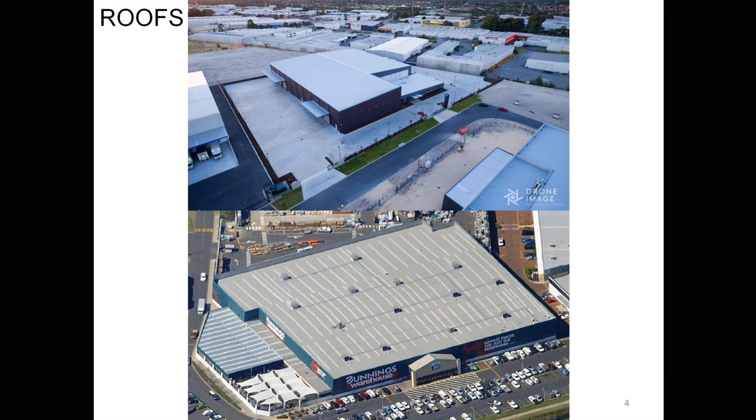Yes, it's called a siphonic system, and of course the most common use of siphonic systems is actually in American toilets. If you ever travel to Southeast Asia or to Japan or to America, they love having these toilets with like a swimming pool in it, lots of water in it. What happens is that when you push the flush, it shoots a jet of water sideways. There's always this kind of opening in the bottom of it, and it shoots a jet sideways, which creates a whirlpool. Then that whirlpool creates suction, which pushes everything out the outlet of the toilet. Of course, the problem there is that there's a lot of splashing, if I might say so. So if you're having a number two, your bum gets wet, which I think is kind of unpleasant, which is why I don't like them.